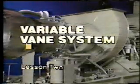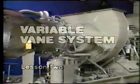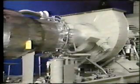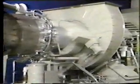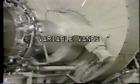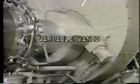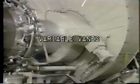Variable guide vane system, lesson 2. In a previous lesson, you learned that the compressor can stall during the startup phase. The variable vanes move between two positions to match the air entering the compressor with the air leaving the compressor. Controlling the airflow through the compressor will prevent engine stall.